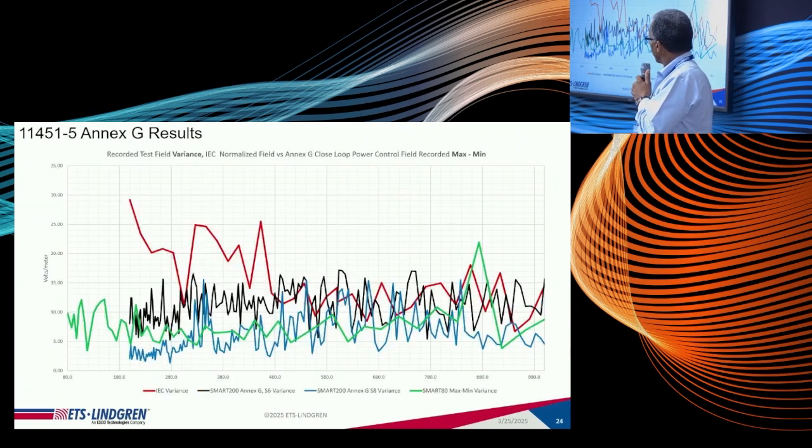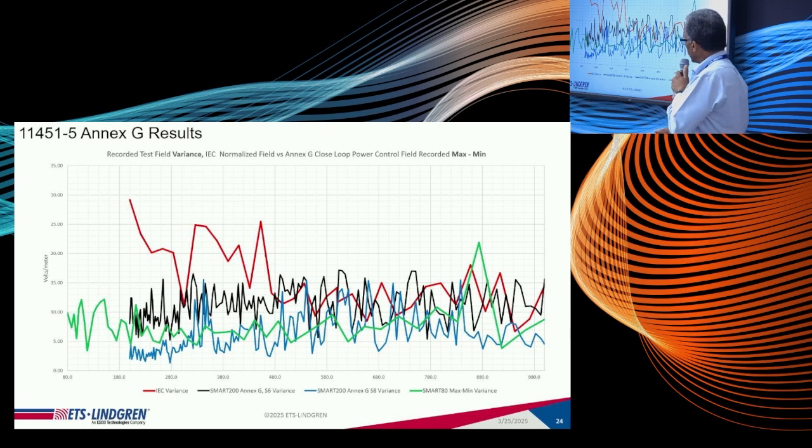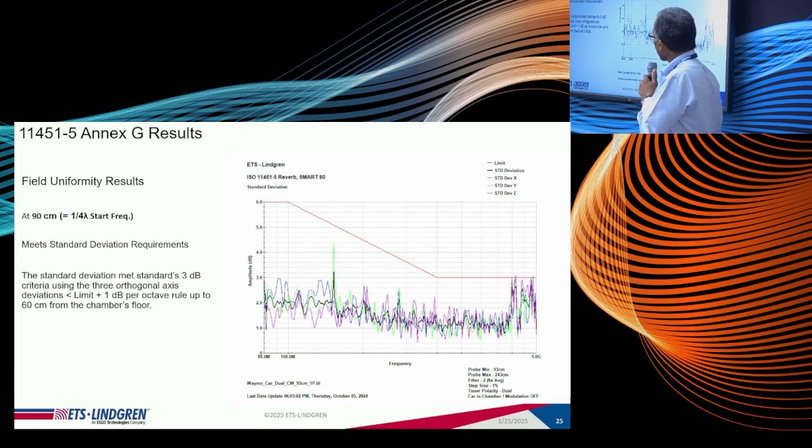And again, compared to the IEC standard, there is fairly low variation in the max to min of the maxes when using that 8 probe ISO setup, compared to the traditional IEC type environment and IEC procedure that was used previously. And of course, the big advantage here again is that you're saving in measurement time because you're doing that analysis and measurement on the fly.